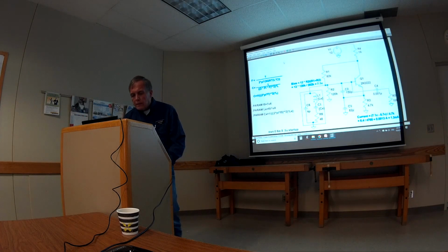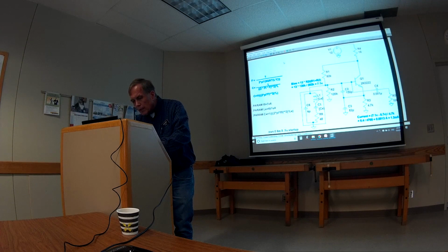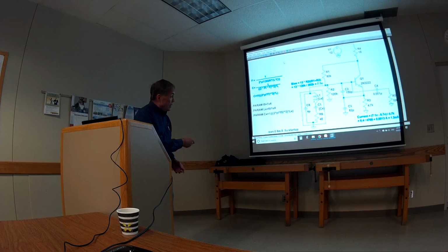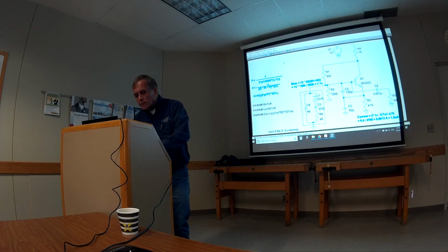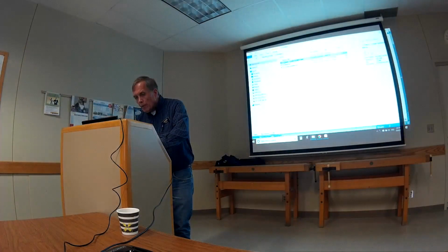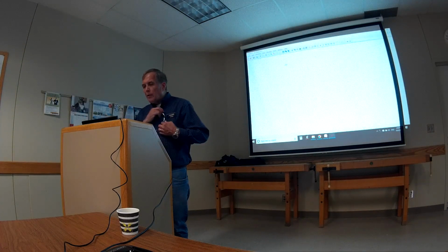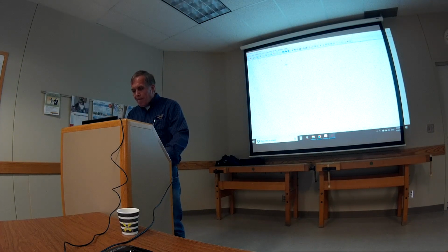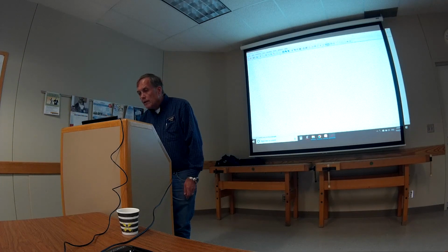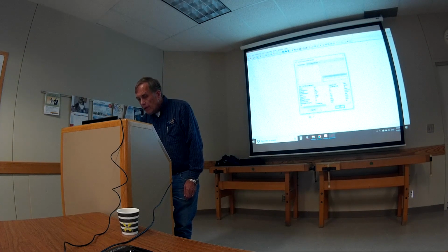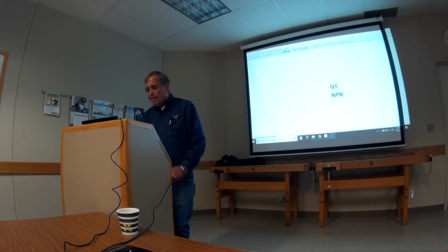This is the same circuit we had. We just looked at all those parts. It has a transient spice directive at the bottom that tells it to run for about 6 milliseconds and so on. But let's start off with a blank, and let's see how we're going to put some of those components in there again. We're going to start out by dragging a transistor. I'm going to find one down here, and that's under NPN, right there. And I'll say OK. I'll plug that right in the middle here.